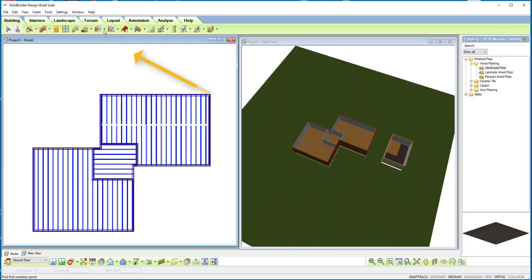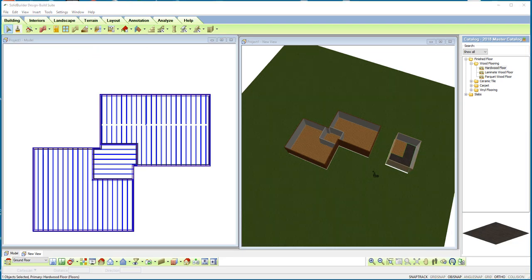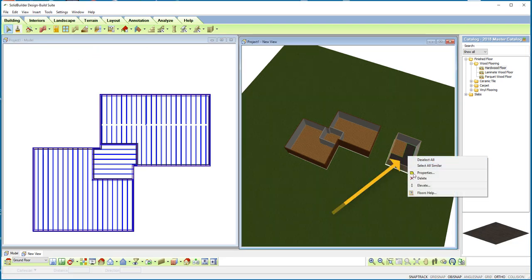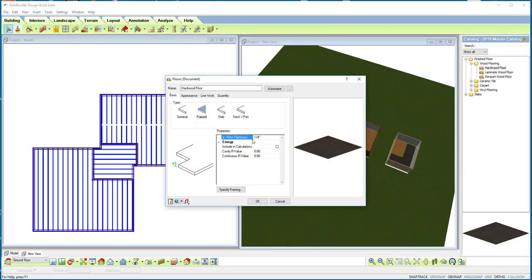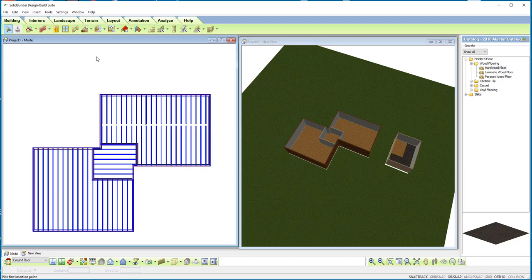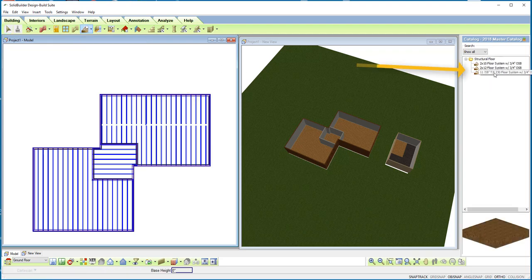The various options that you have are the basic floor by default, by room, perimeter, pick points, or that room division option. And you can also select and right click and go into properties with that basic 1/4 inch tool and switch it to a framed option. And then you have the structural floor by perimeter, by room, and by pick points, where you choose from the catalog the floor system you'd like.